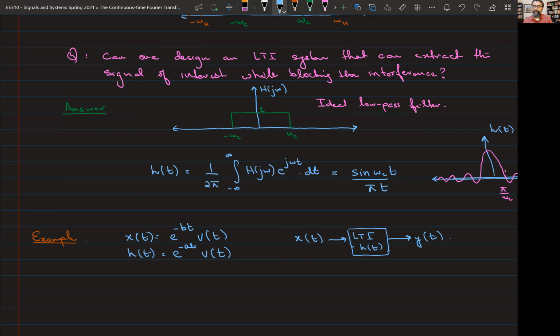Now, one of the ways to do this is to go into the Fourier domain first, right? Do that multiplication and then compute the inverse Fourier transform to get what the convolution would have been, right? It's just like that example that I gave you earlier, right? In order to find solutions in country A, you often have to go into country B, which provides you with a shortcut. And this frequency selective filtering, the idea that I just mentioned up above, is exactly that, right?